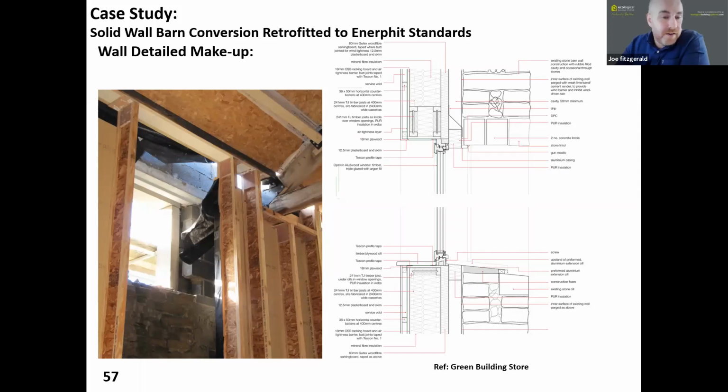So they're going to fit cellulose insulation between that once the vapor control air goes on inside. And as you might see between the studs, you might see the wood fiberboard backing. That's a secondary insulation on the back of the stud. Okay. But the big question was whether or not they would get away with leaving the void between the stud and the wall exposed, unventilated.